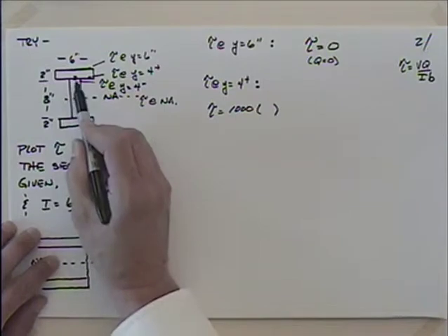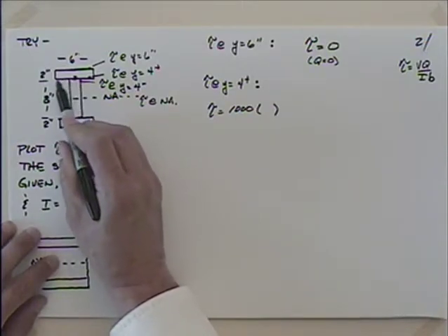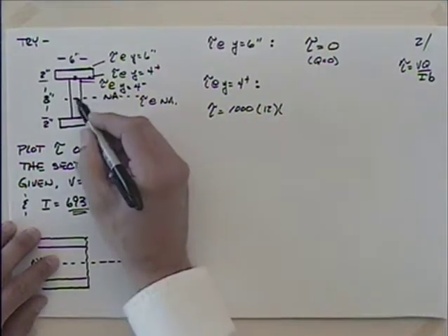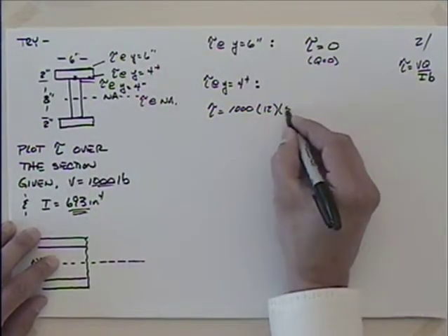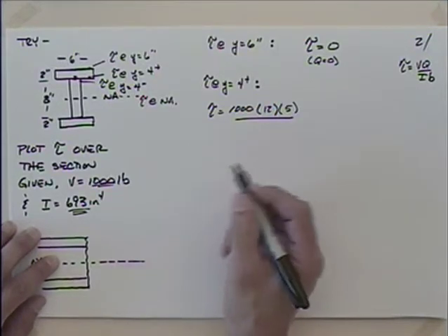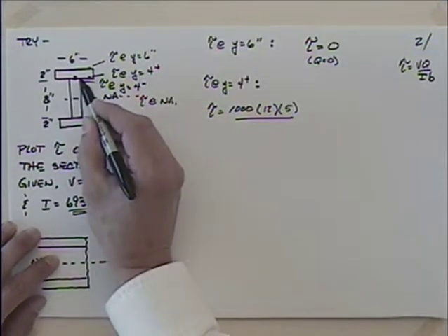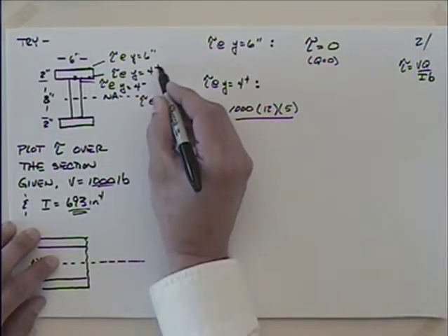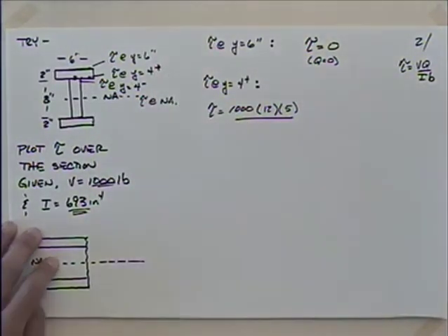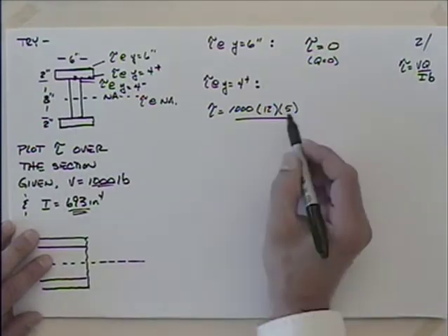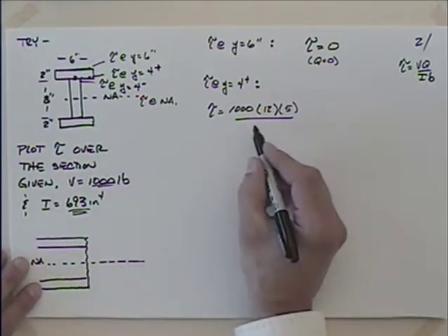Well, what's the area above there? 2 times 6, that's 12, times what's the distance? 4 plus 1, 5. Is that right? Because you might say, well, doesn't the area change because we're slightly above there? Well, we're talking about plus like 0.00000 something. We're just barely up into that flange, so it hasn't affected the area, hasn't affected the distance to the centroid.